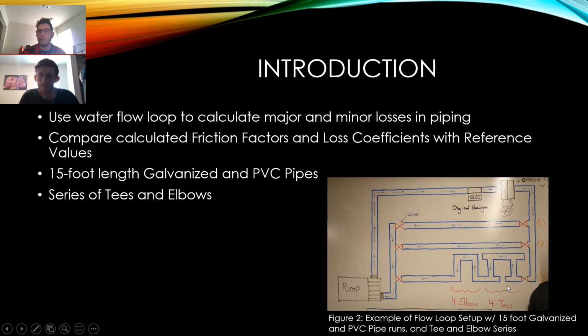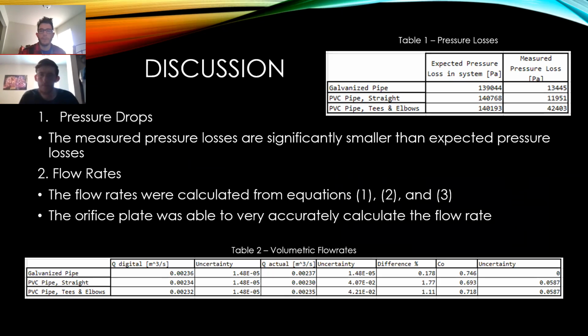were interested in, like the 4 elbows, the 4 T's. We didn't take into account all of these other elbows, like this first one here coming out, or this one here in the back, or any of the valves or any of the screens throughout the system going to the pump or the valves, wherever they might be located in the system. So those play a significant role in increasing the pressure losses to the system, but we just did not take into account those. As JT was talking about earlier, the 4 L's and the 4 T's had those pressure differential meters on them so that we could tell those differences, but there's a lot of geometries and other things that are unaccounted for causing this significant difference.